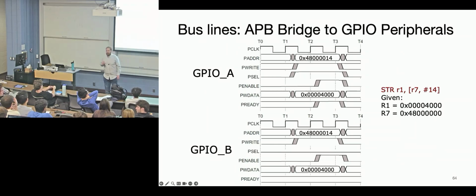Have we ever done an example, in terms of a design, that makes it so that P ready has to be low for X amount of cycles and it's waiting? We had an example of what a wait state would be. I don't know if you had an exercise on exactly that. So one common way to do it is some magical peripheral, I think you saw this in one of the exams, right? Has a line that says if it's high or low, it's ready or not. And then that would be the indicator that the peripheral is not ready to finish its task.